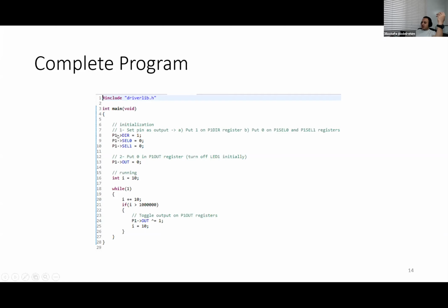Okay, so this means port 1 direction register equal to 1. So here I am putting 1 in this direction register. What does that mean? That means this is 8-bit, I will write 1 in the 8-bit direction register. So it will be 1 0 0 0 0 0 0 0. 1 and 7 zeros beside.